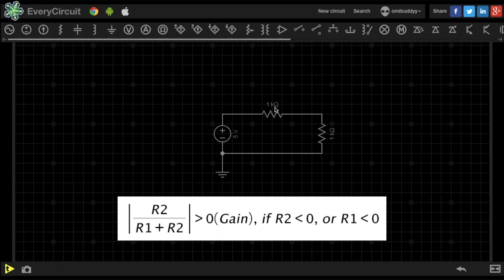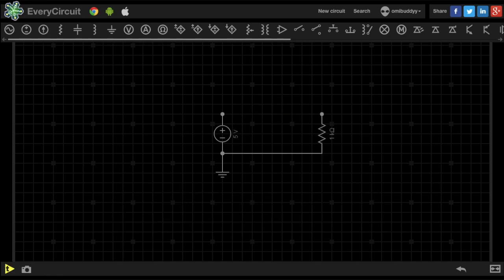What is the meaning of this? Let's remove R1 and replace its position with a negative R1, but we don't know how to realize negative resistance. Rather, we don't know what the meaning of negative resistance is. So as of now, let's think that there is a black box which does this for us. If you think about what this black box needs to be doing, it should basically add voltage over the input voltage so that we can get gain out of this circuit.